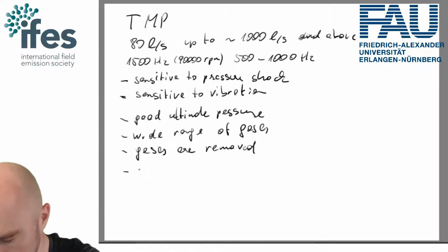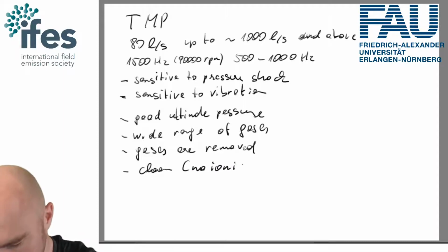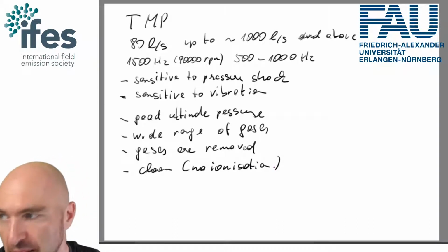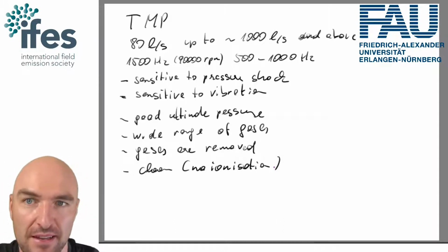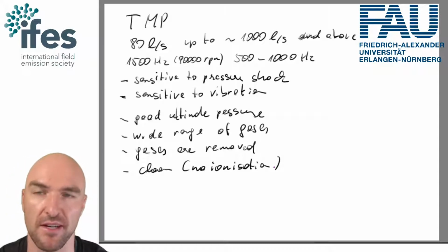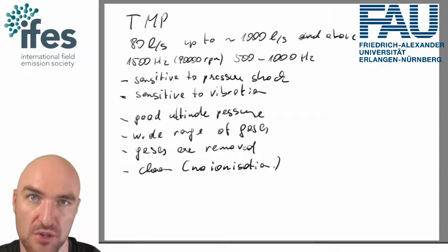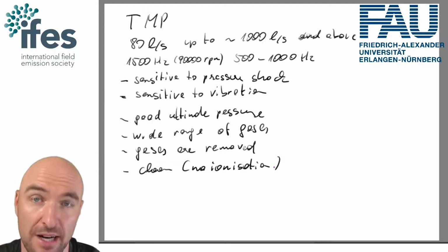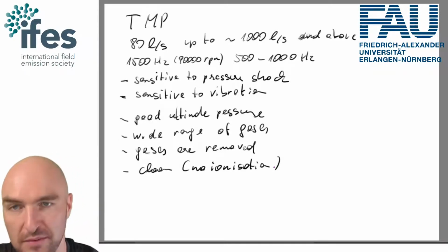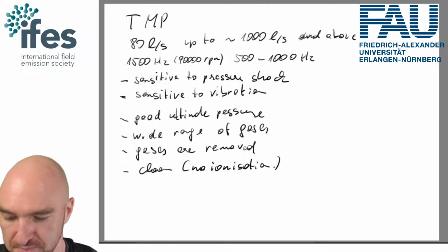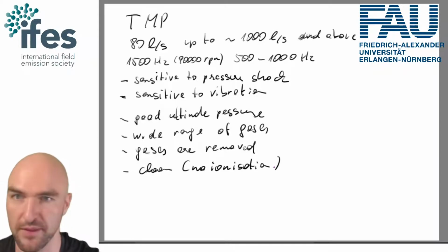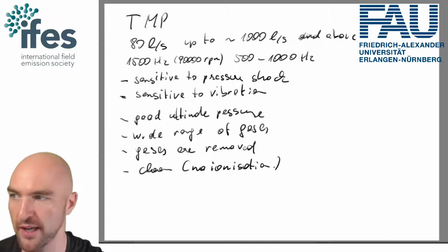The other thing about them is they're very clean, so we have no ionization. Some of the other pumps that you will see, ion getter pumps, can lead to ionization. If you have some contaminants, they're not a problem just by being there, but once you ionize them, like hydrocarbons, they become a problem. You're not going to have that problem with a turbomolecular pump. Good, and with that, let me show you a turbomolecular pump.